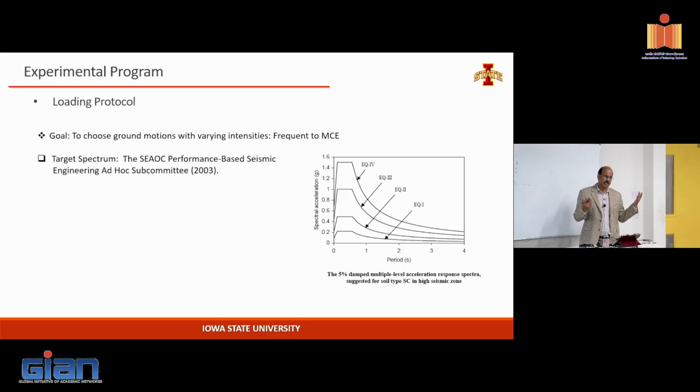Both have significance, right? Recorded earthquakes have significance because they have their own characteristics. Simulated earthquakes have significance because you can match the simulated earthquake to the target spectrum, so you're not exercising unnecessarily or putting too much energy into it.